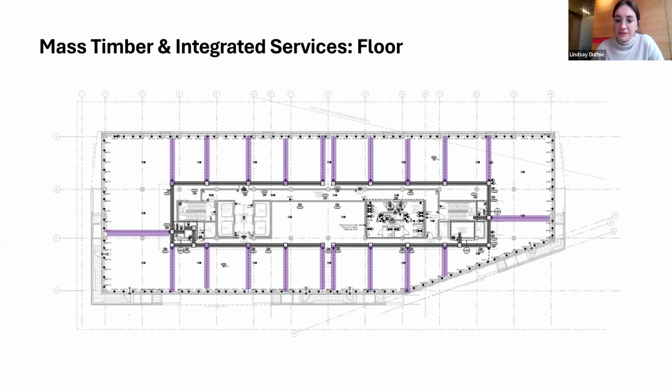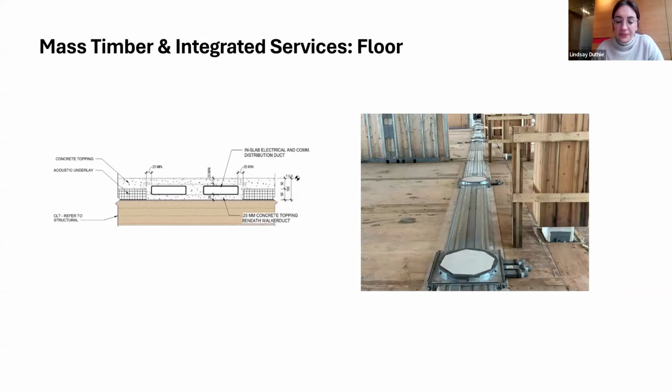And then in terms of the floor, we do have a Walker duct system. These are highlighted in purple. This is integrated into our floor topping, and this allows future flexibility for the tenant fit-outs to have power where needed at the perimeter sill wall.